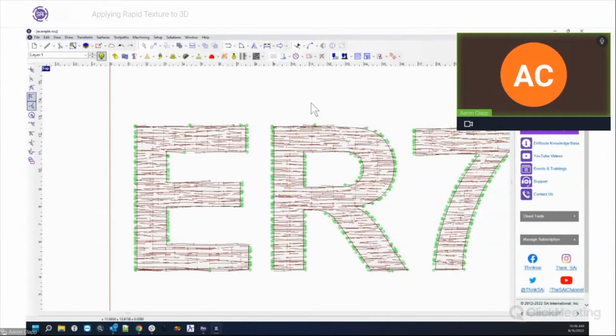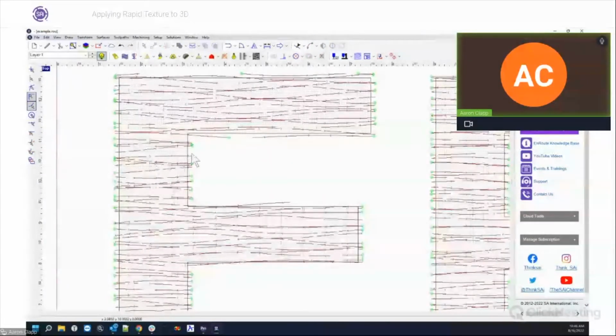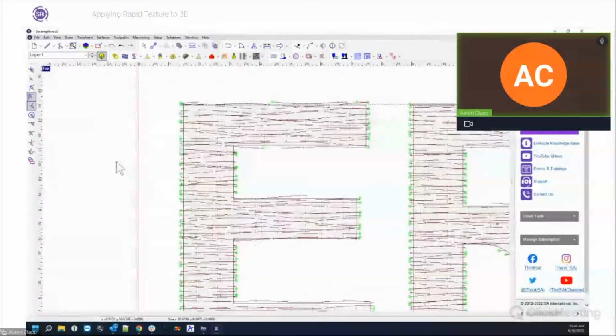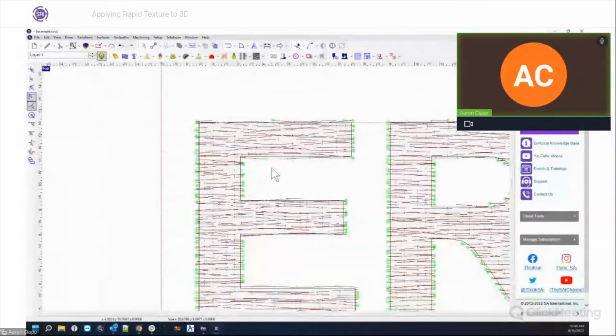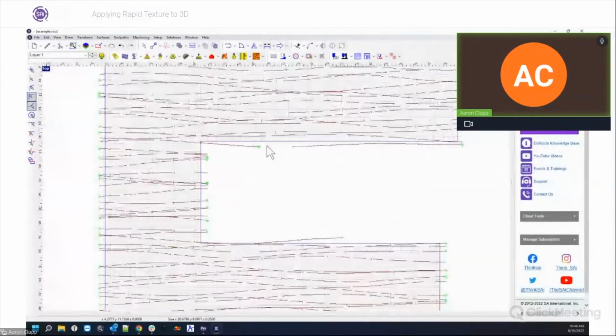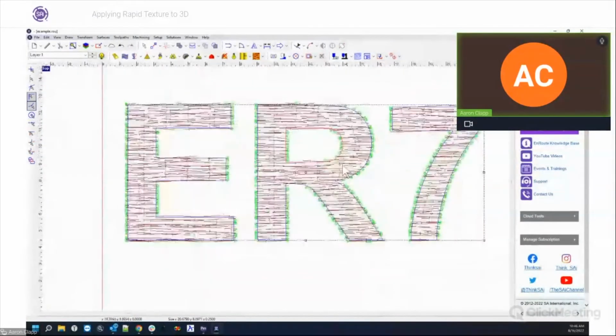We've got our toolpath now. And then I'm going to start putting on a toolpath for my 3D. So I'm going to zoom in here, make sure I have my 3D selected here. Oh, you know what? I need to turn off my layers because it was selecting the part that was in the second layer there. There we go. Select my relief. So now it shows blue and red.